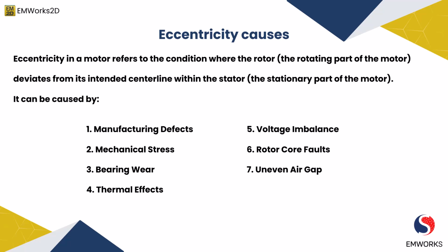Eccentricity can result from manufacturing errors such as misalignment of motor parts during assembly or inaccurate machining of rotor or stator components. These defects can lead to uneven air gaps between the rotor and stator, causing eccentricity.